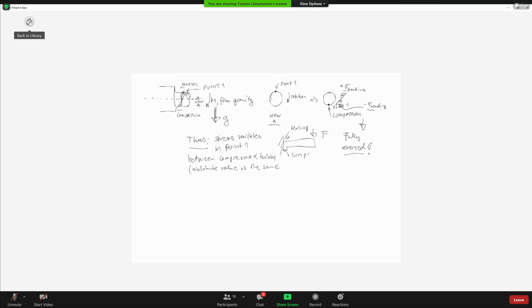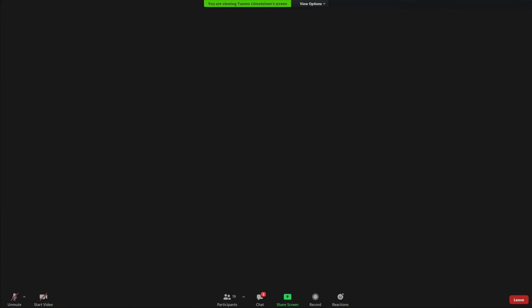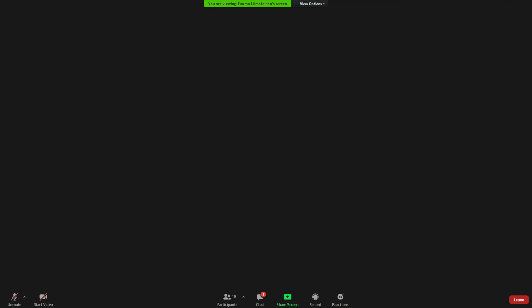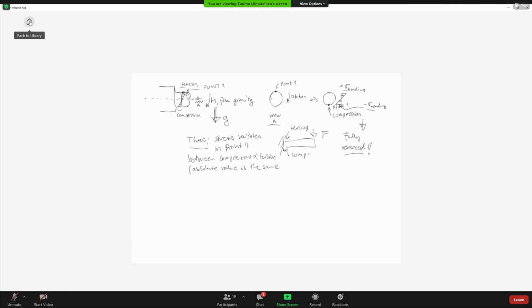So just to make it clear about the mean stress: we use mean stress in stress oscillations, so to say, to define the average stress. Or am I wrong? Well, the mean is the one which is the middle of the oscillation. So in this case, if you would only have this load case, the mean stress is 0, right?